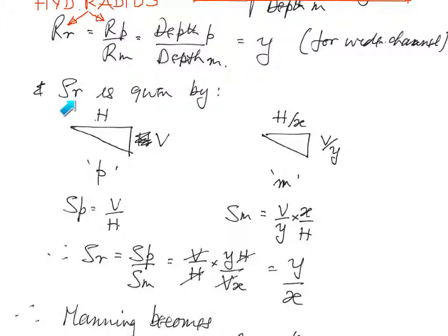The ratio of the longitudinal bed slopes, something that occasionally we might be asked to check, but we don't normally need to work it out unless we're asked. But how would we estimate that? Well, we just consider the longitudinal slope of the full scale channel. For every horizontal distance h, the bed is going to drop by an amount v.